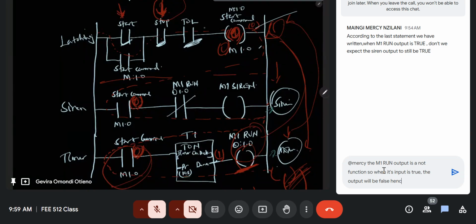So it's a quick scan to know what is the current state of each input and output in this device. Once that is done, it quickly knows what instructions were provided at the inputs, so that it can execute those instructions quickly. Those instructions are like transfer logic 1 to the output, transfer logic 0 to the output, and stuff like that. So it will even know the output logic, but it is not updating those until it finishes the first scan. So within the first scan, remember there's a read.